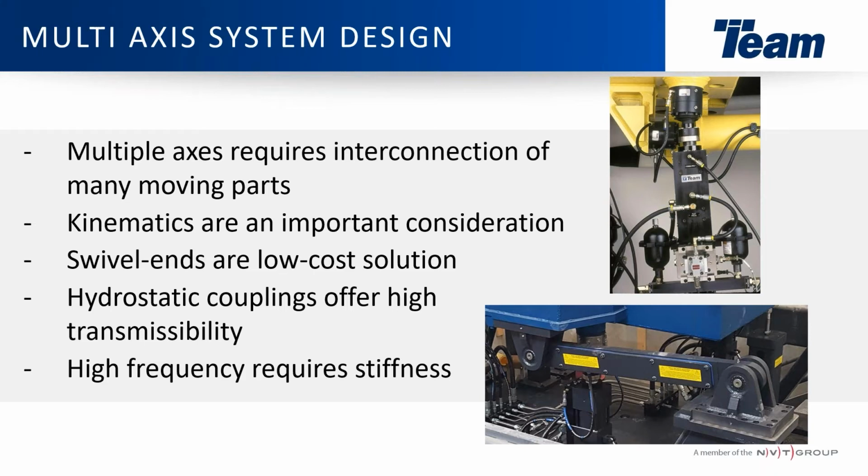When you're doing higher frequency testing, it could cause issues with the fidelity of the test, as well as issues with the actuator over time, and the thin neck of the Hydroball presents higher frequency issues once you get above 250, 300 hertz.